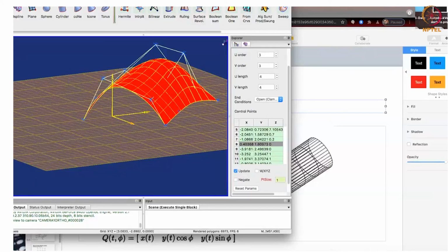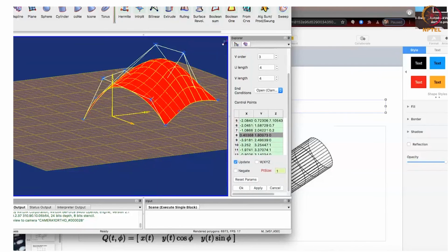You can arrive at the control points. For example, you can equate this bicubic or a cubic B-spline, and then you can equate your cubic spline equation, and then you can find equivalent control points for the cubic spline curve that you have. So that is possible. It is definitely possible that you can do that. Maybe I'll show some other demo on that.